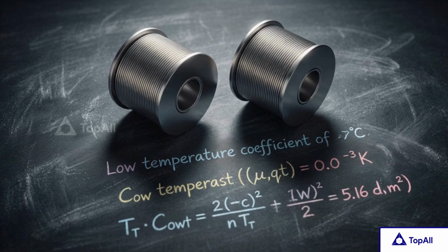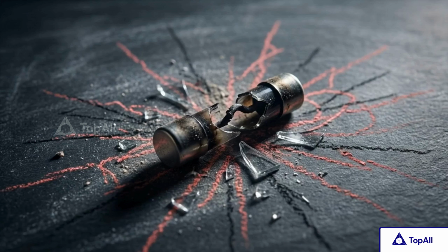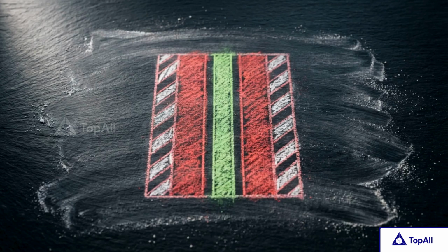Alloys like nichrome and manganin are used for resistors because their temperature coefficients are exceptionally low. Nichrome, an alloy of nickel, iron, and chromium, maintains its resistance value even when heated. Once a standard conductor enters that curved region of the graph, the simple V equals I times R equation fails to predict circuit behavior. Proportionality in physical conductors is a narrow operating window that collapses under thermal stress.